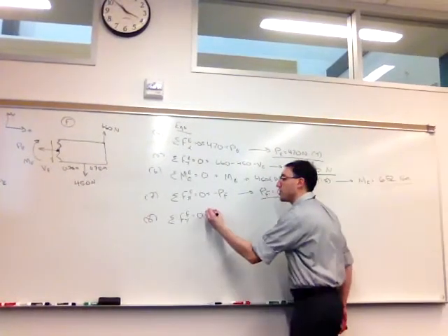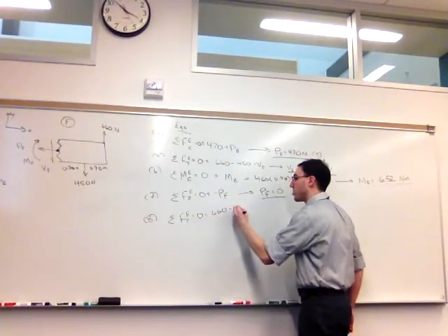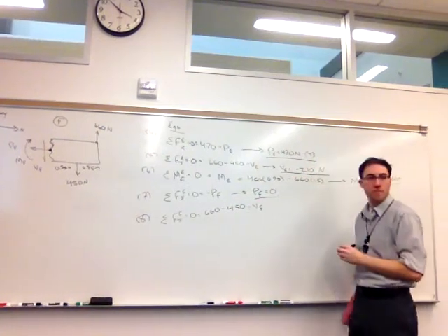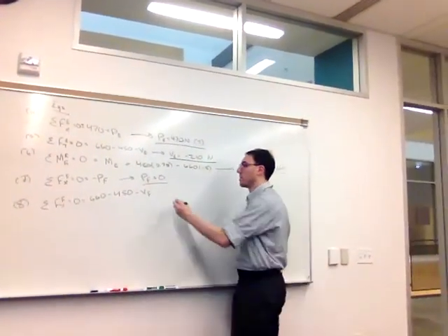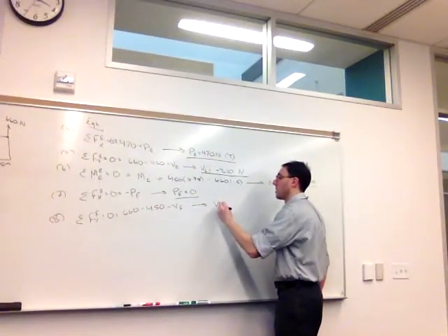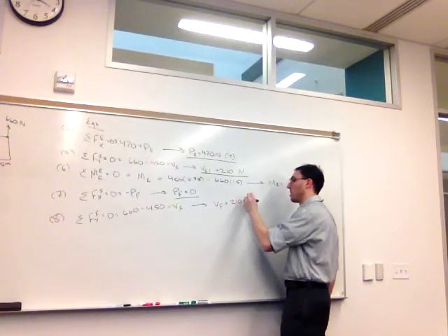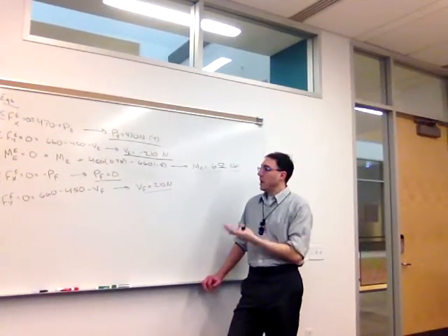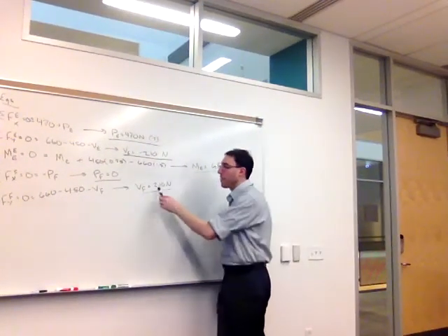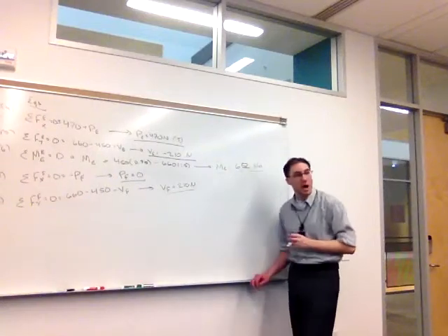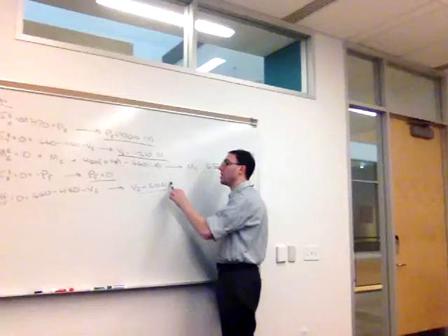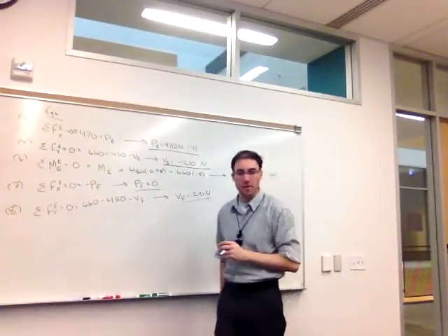In the y, we have the tension in the rope up. We have the distributed load down. And by my assumption, we have the internal shear force down. So at point F, we get positive, by this assumption, positive 210 newtons for the internal shear force. Same magnitude, but the sign actually does flip.